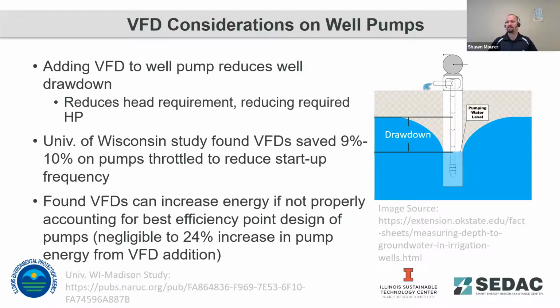But if your pump isn't properly selected or designed for application with a VFD, there is a potential here to see an increase in energy consumption by applying a VFD. Because as I noted in the high service head chart, the pump's efficiency drops off as the pump's flow rate is reduced, as pump speed is reduced.